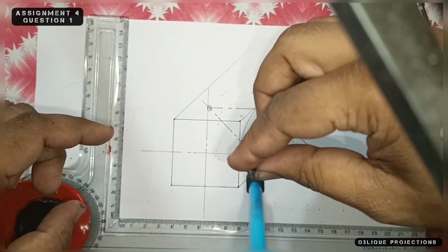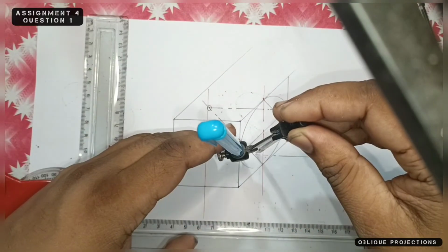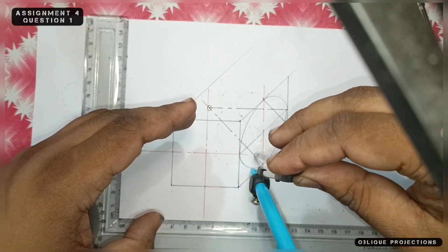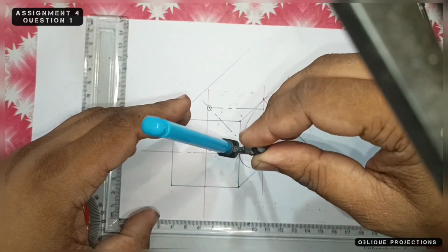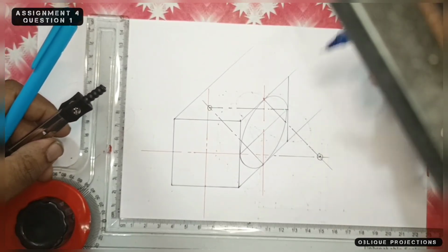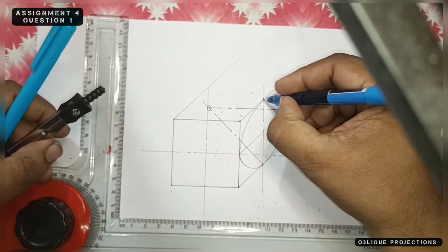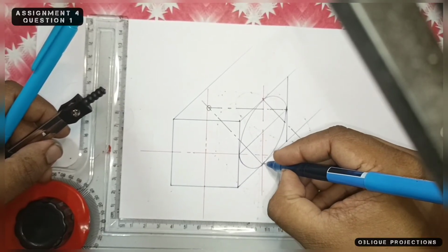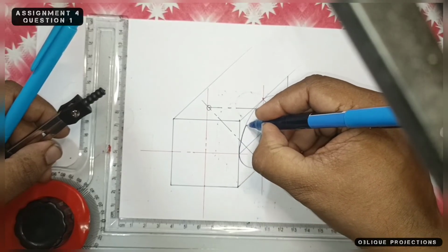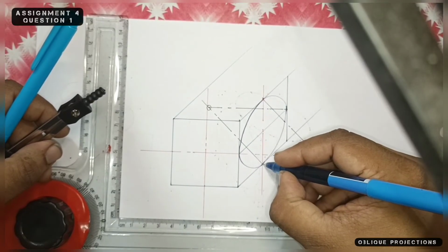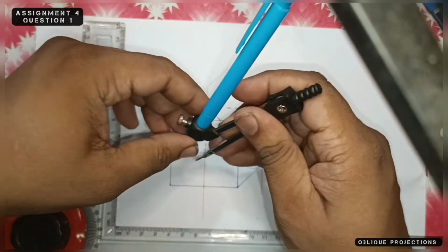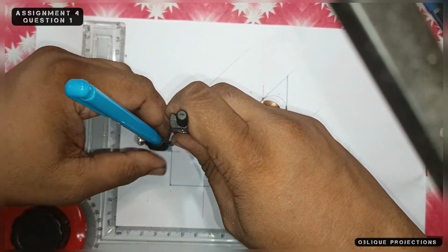Now put this circle, because if you have drawn it very carefully, then you may find zero error in this construction. So there is a little bit of error over here. The rest of the figure is almost at zero error. So you can find this method is called the approximate 4 center method.